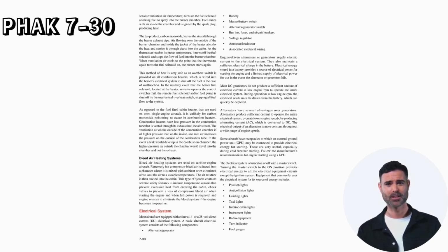This type of system contains several safety features to include temperature sensors that prevent excessive heat from entering the cabin, check valves to prevent a loss of compressor bleed air when starting the engine and when full power is required, and engine sensors to eliminate the bleed system if the engine becomes inoperative.